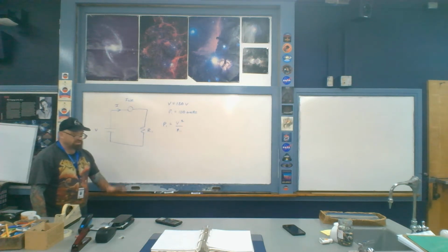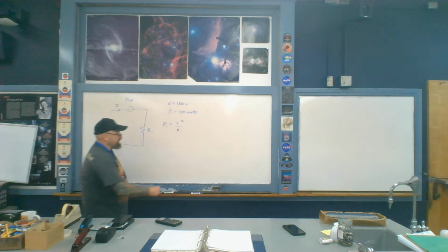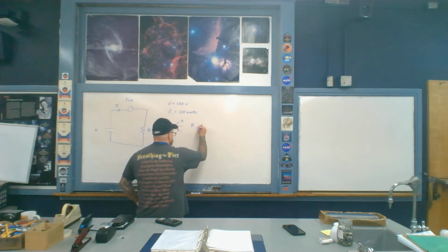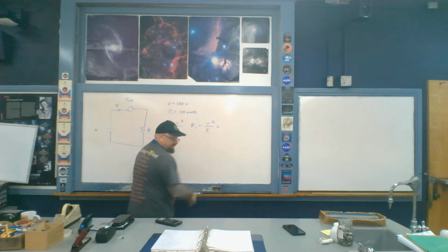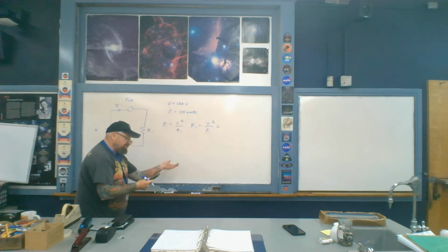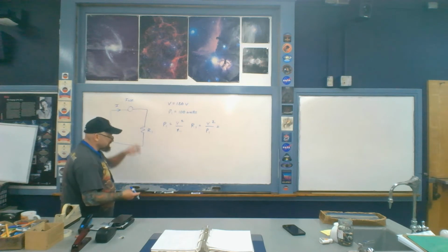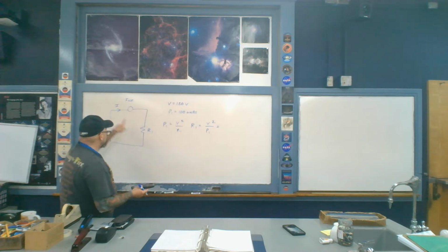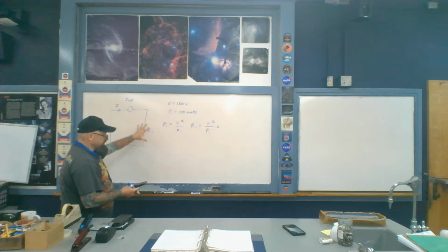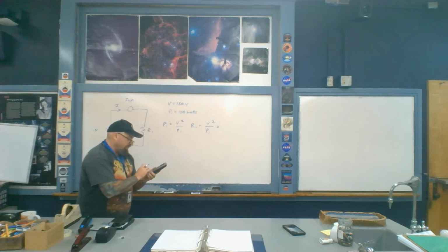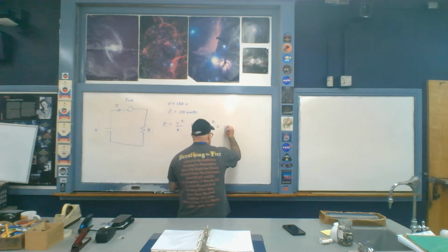And now let's go ahead and just calculate what the resistance of the light bulb is by doing the following. Cross multiply, like so. And now let me go ahead and find that number. I'm going to use this number then to calculate the amount of current that is going through this resistor. Ultimately, that's the same as the conventional current I here for the entire circuit because we only have this one thing on. All right, so 120 squared and then divided by 100.